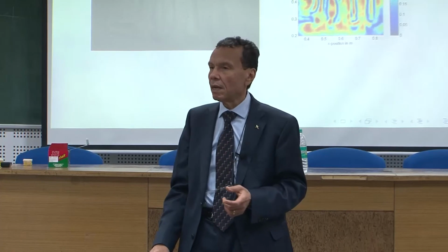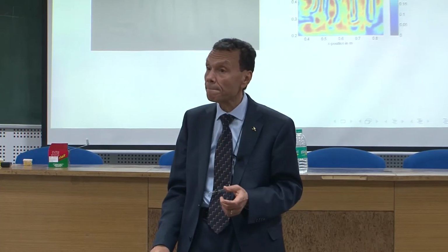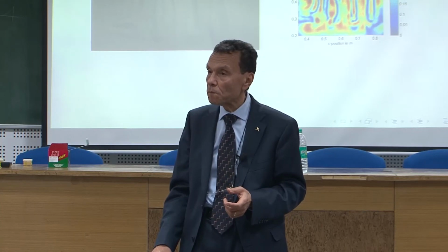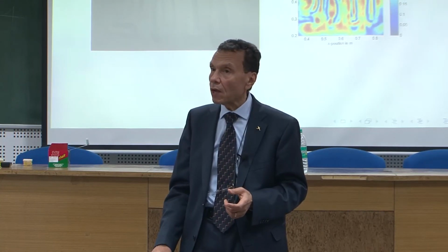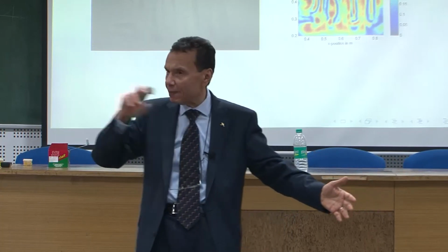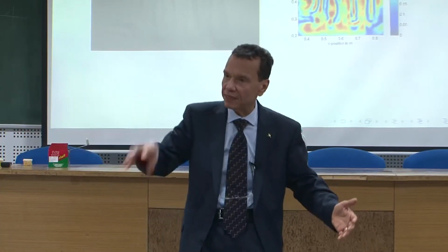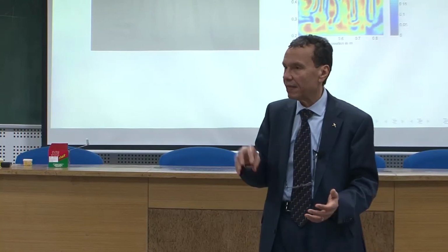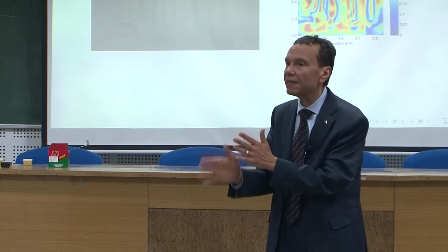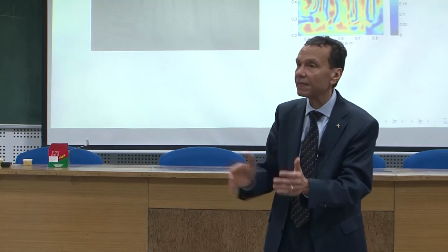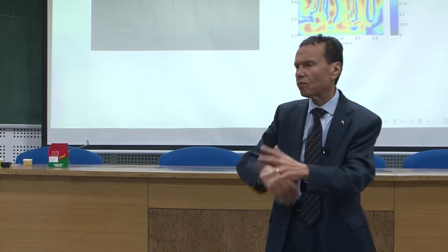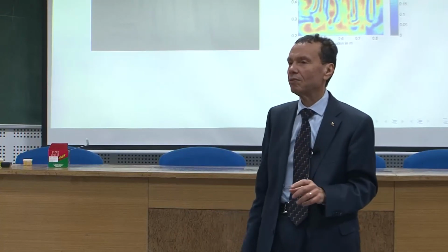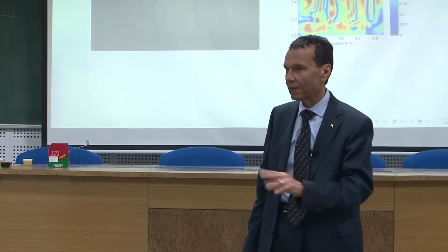But if each element is omnidirectional, then in order to achieve a narrow beamwidth, a larger number of elements would be required, right? Or a bigger area, because actually the elements are the positions at which you stay and measure. And of course the distance is the d in your antenna pattern, and you can relate this to aliasing, to grating lobes, and all what you learned in your antenna lecture, you can apply it here.